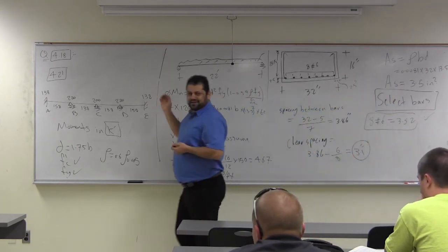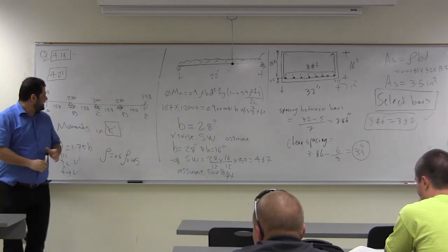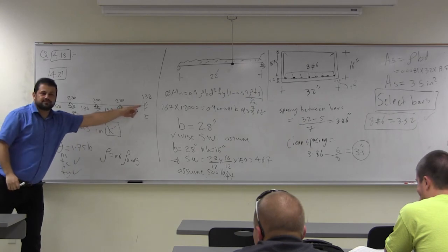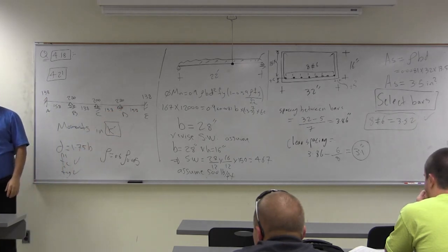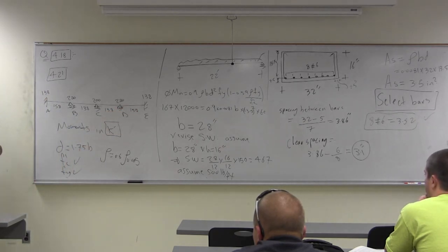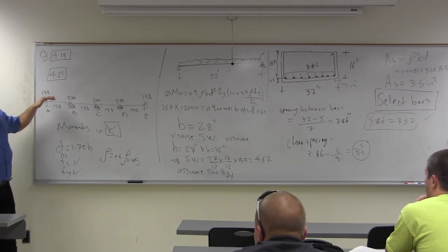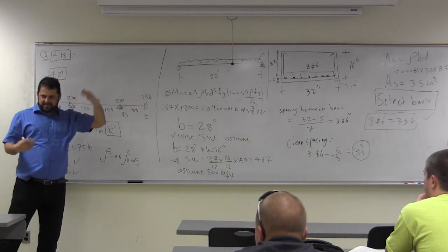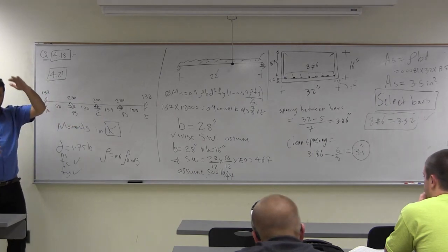So we have moments here, right? When you have the moment at the support, guys, the moments at the support are what? Negative or positive? Yes, have courage, you cannot miss this. Negative. It means tension at the top. It means where is the location of the steel at the support? Top. Negative moment, tension at the top.